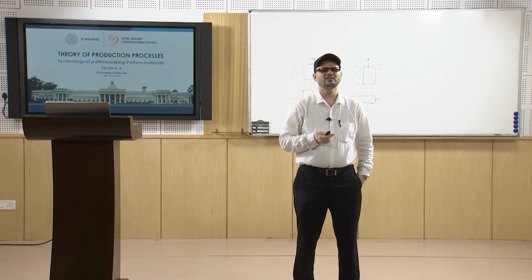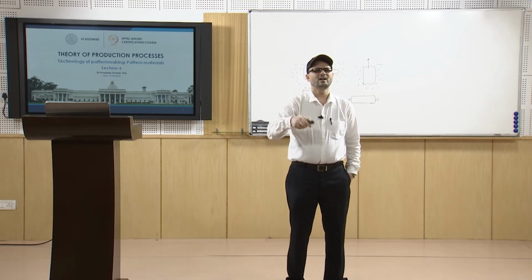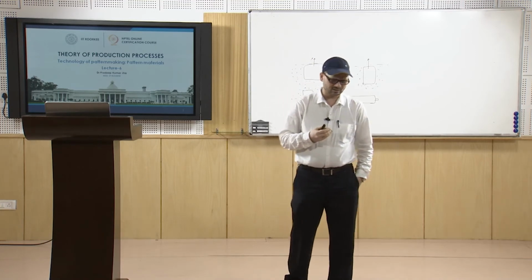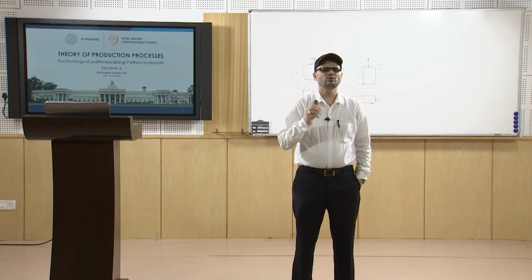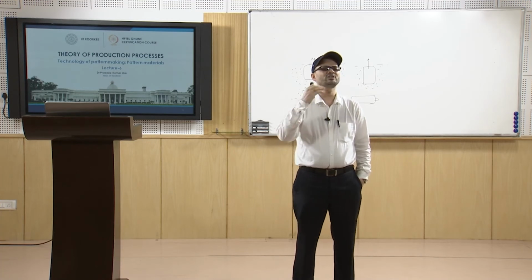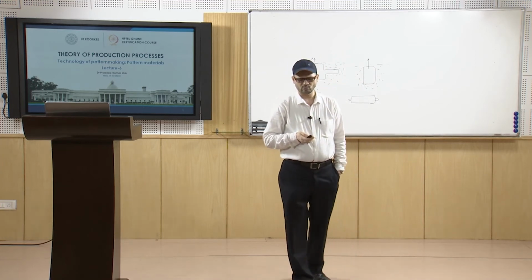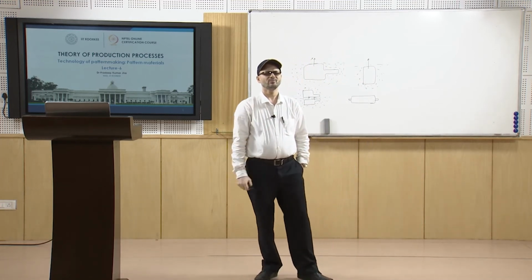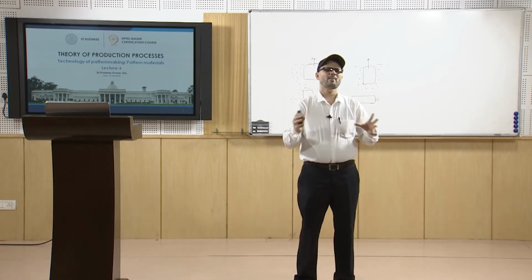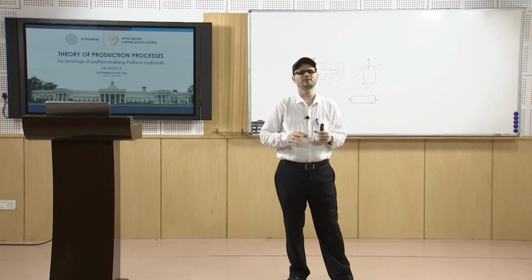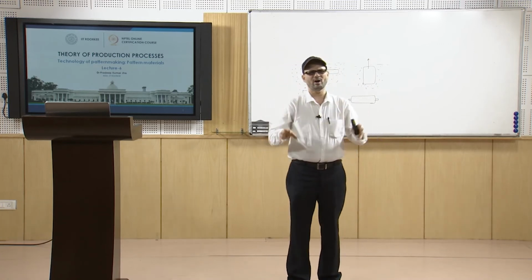This is the best choice for pattern work, and for when you have the pattern required to be used in the molding machines. So, permanent production work on molding machines is required. In that case, wood is preferred. As we discussed, wood has one disadvantage: because of the change in humidity and the change of weather, it may distort or warp.